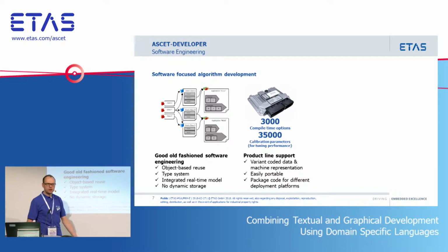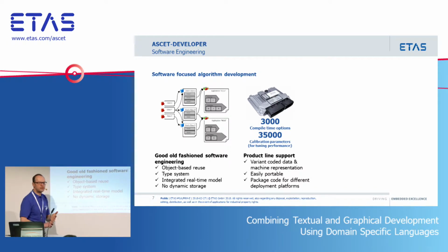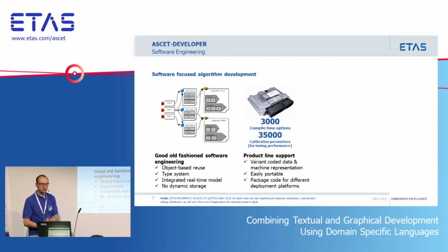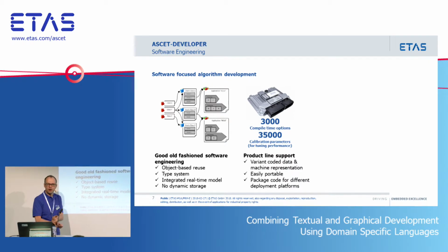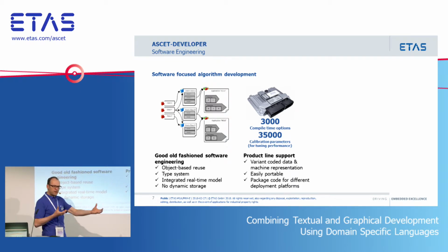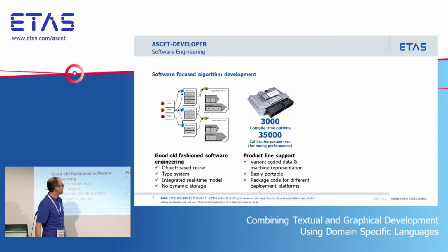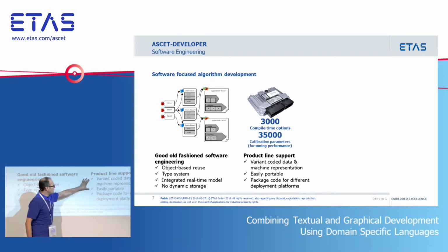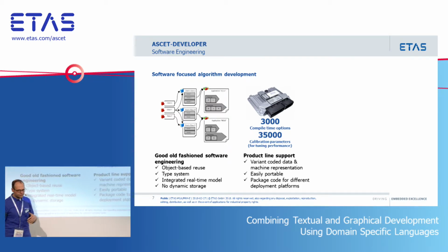And a variation might be about how numbers are represented. It might be where data is stored. So is it in near RAM? Is it in far RAM? Is it in Z data section? You know, these kinds of things. Is it on core A? Is it going to be core B? How do we calculate things with costs of fetch and things like that? So we can calculate all these variations in here.